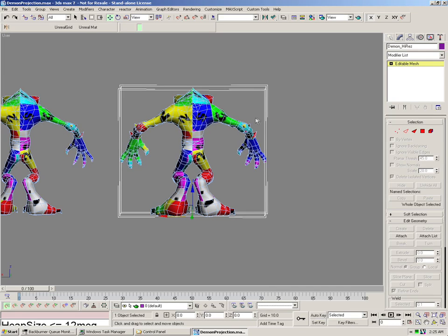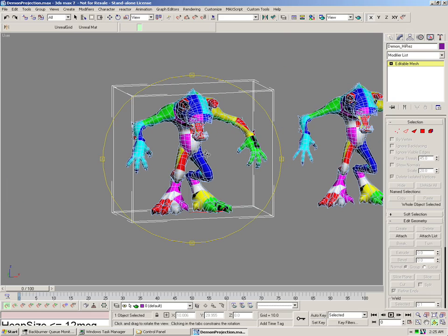This is actually the very high dense 2.2 million poly model, and I've set that to view as box so that we don't have viewport problems, so that we can actually work in the file interactively. That's also another good tip for you guys, is if you're bringing in very dense models into 3D Studio Max, it's a good thing to just go ahead and turn off display geometry in your viewports before you import that. That way you'll get a much quicker refresh of Max after it imports. It won't have to wait for the screen to redraw after it imports these huge models.